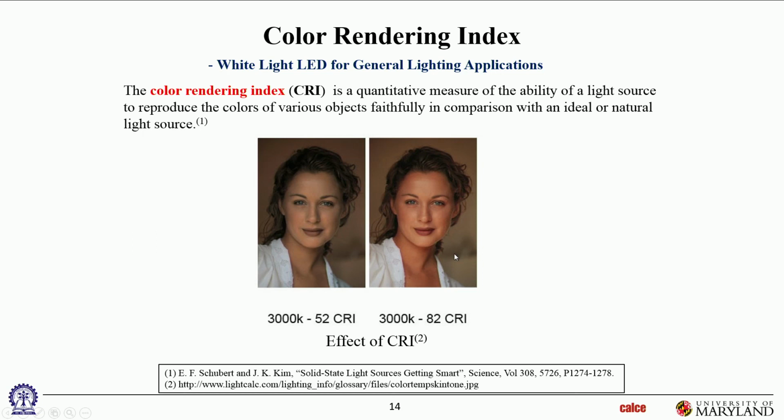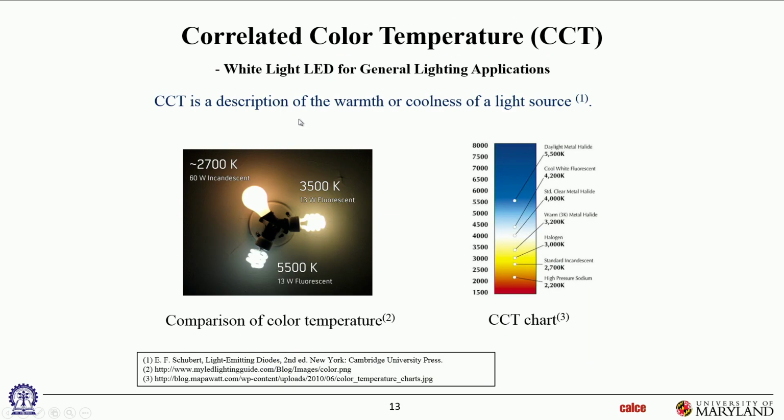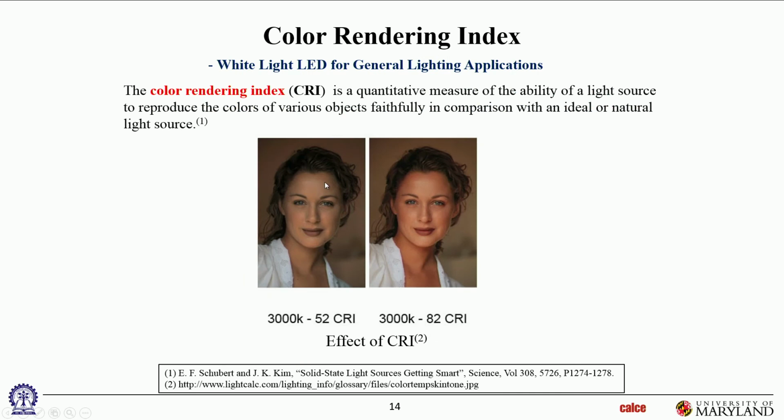So it's not just the color, like the example I gave from blue light to yellow light, but even within blue light, depending on the shape of the spectral plot, the color rendering index varies. All of these are specs. So if you buy an LED lamp, or you're going to spec an LED lamp, you would say what frequencies you want, what